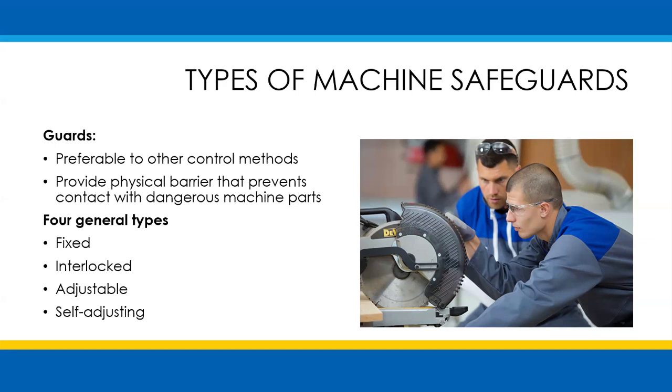Guards typically are designed with screws, bolts, and lock fasteners, and usually a tool is necessary to unfasten and remove them. Generally, guards are designed not to obstruct the operator's view or to prevent employees from doing a job. Guards must not create additional hazards such as pinch points or shear points between guards and other machine parts. Guard openings should be small enough to prevent employees from accessing danger areas.